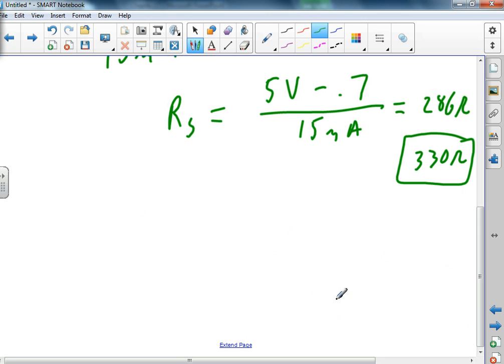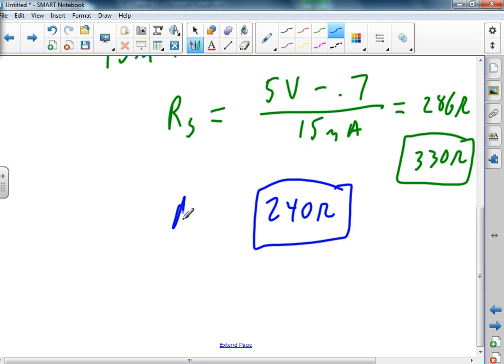And then when we put it in Multisim, the Multisim light emitting diodes weren't turning on, and the reason they weren't turning on is because our regular light emitting diode turns on over a continuum of light. In Multisim, the light emitting diode is either on or off. It's a digital thing. So we ended up putting 240 ohm resistors in our circuits when we build them in Multisim in order to allow the light emitting diode to come on.